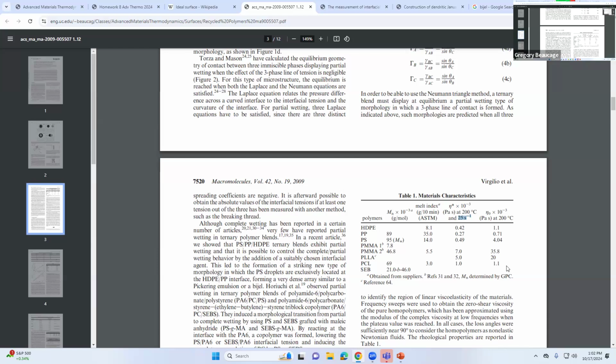Like when you stir up egg, it thickens as you stir it. And then there's a couple other viscoelastic kinds of behaviors, but shear thickening usually means that the structure changed. It's kind of a permanent one-way street thing. Shear thinning is reversible, also structure changing. Anyway, he measures all that.